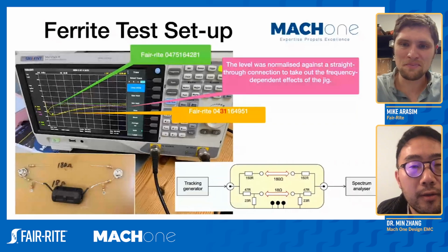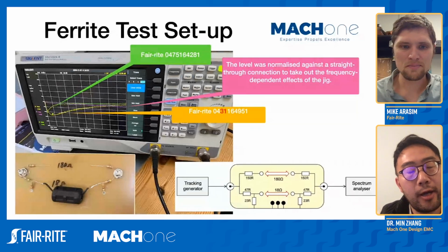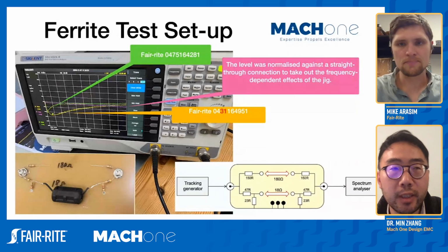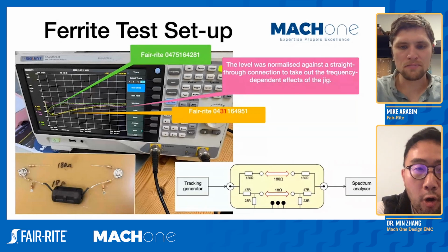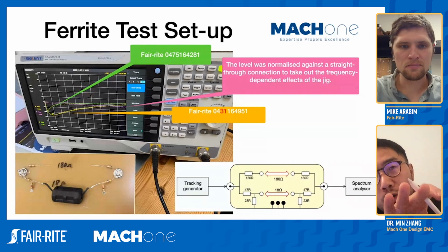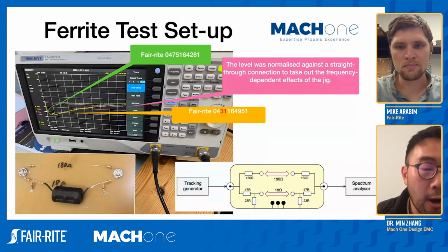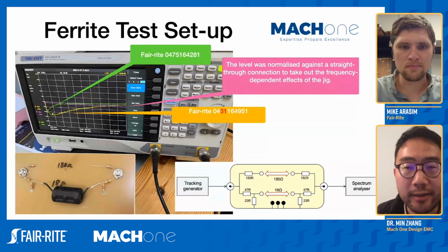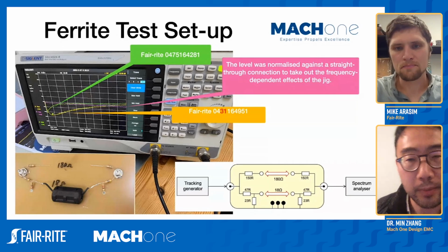Yeah, exactly. This also reminds me that filter companies, companies that sell a filter as a solution, often test with 50 ohm source impedance and 50 ohm load impedance. But then they also often do 0.1 ohm as the source and 100 ohm as the load, and then 100 ohm as the source and 0.1 ohm as the load, trying different combinations. As we explained, that's just going to the extreme, but in reality we never know what the source impedance or the load impedance is.